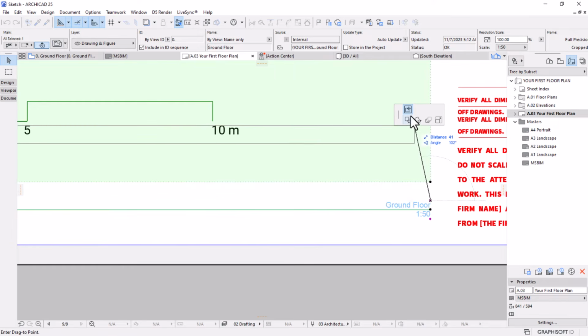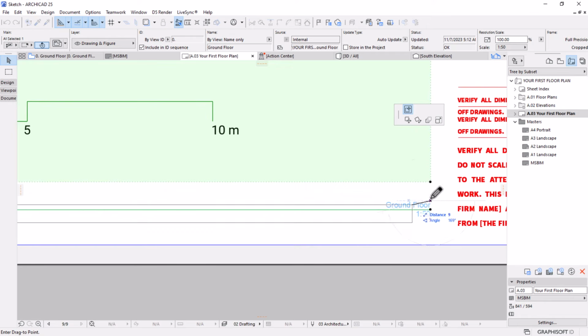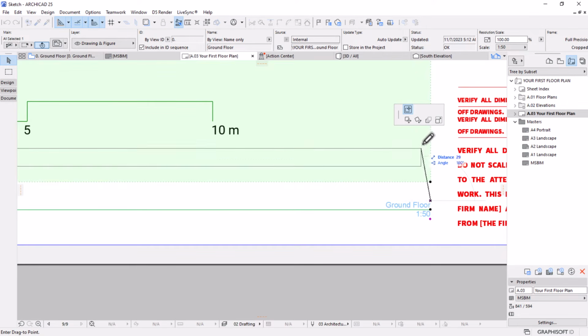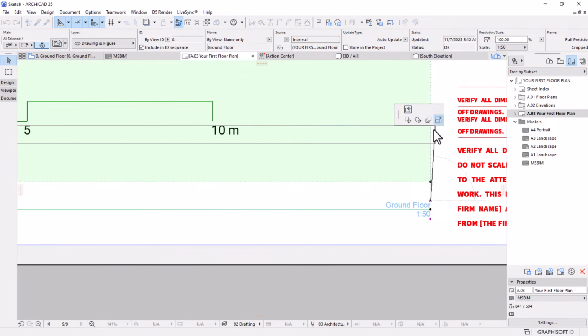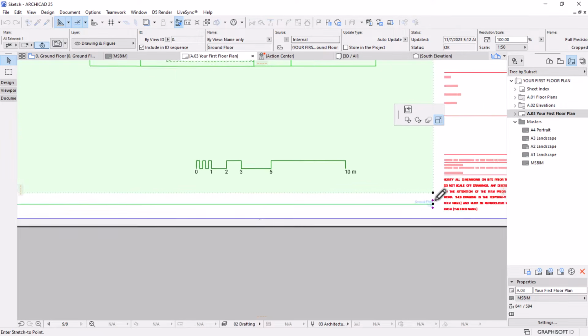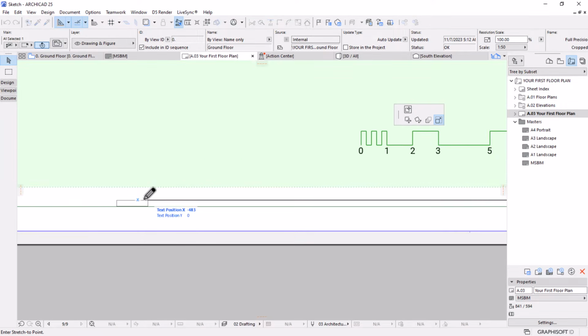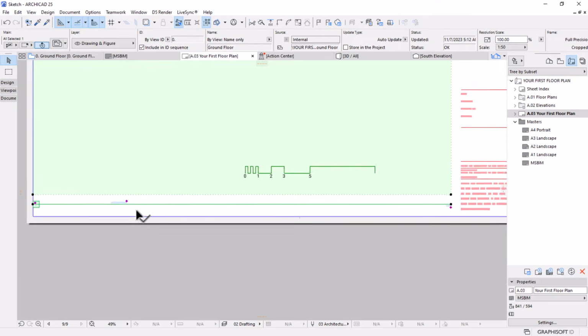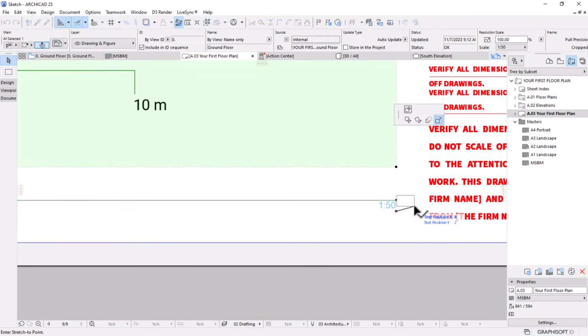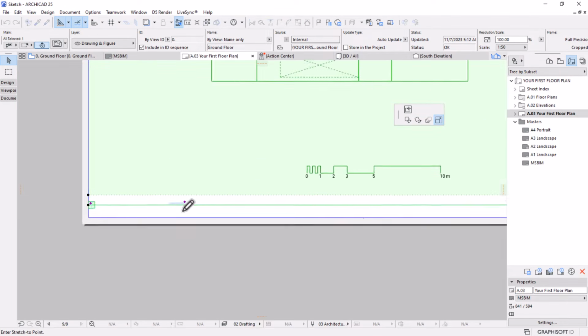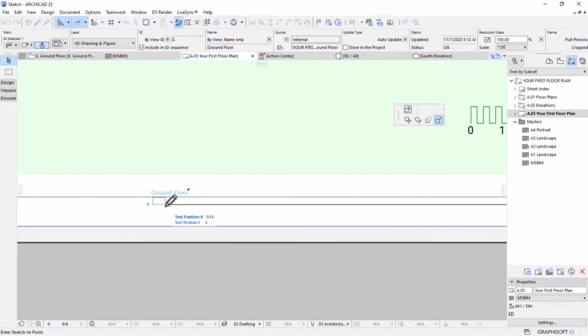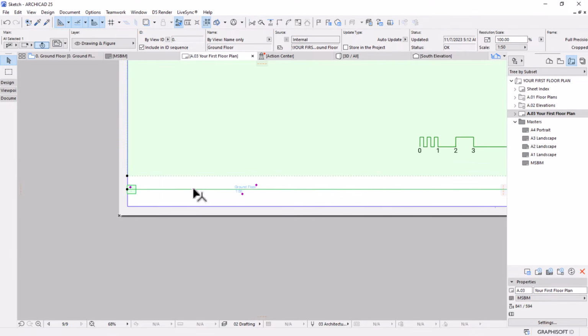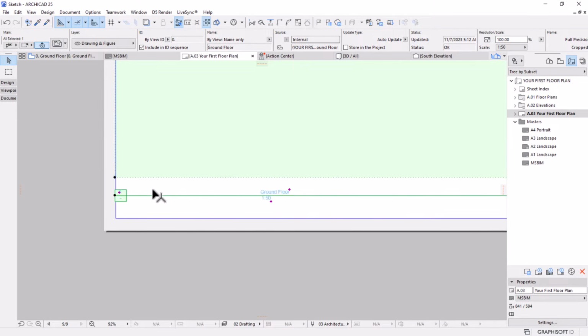So I need to change, instead of moving the sub element, because here the sub element is the drawing title, the actual drawing title. So I need to use this one, which is stretch, because I want to stretch it from this to this point. For example, do the same to the scale. Let's just move it maybe along, yes, just to align it with the ground text.